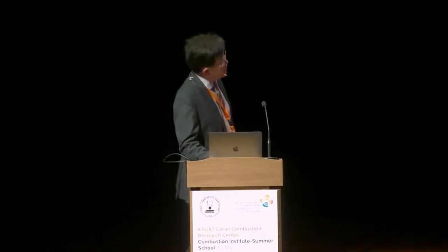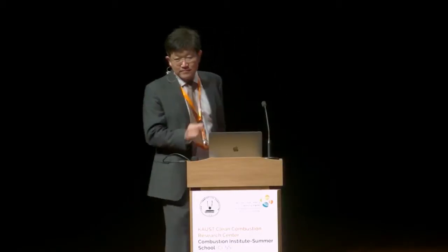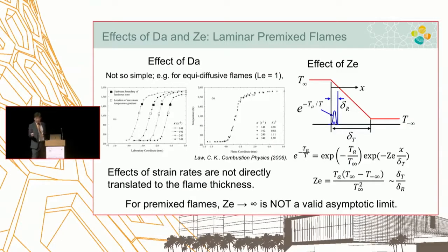Which means that even if the temperature profile is roughly approximated like a linear function, the reaction is focused within a very thin layer. Again, it's very important. The reaction source term in the governing equation is always a pain. You have to deal with that. If you don't have to deal with it for 90% of the zones, that makes our life a whole lot easier. So this is the concept of the asymptotic flame structure.